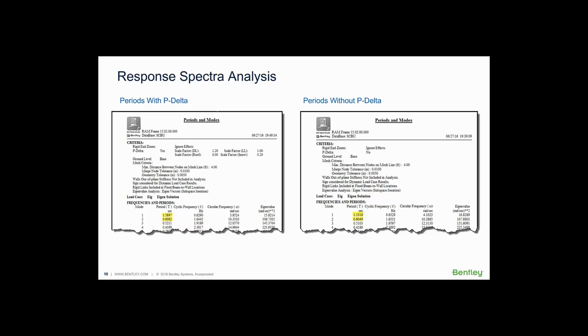That's what that B2 is attempting to measure. It's attempting to measure what my moments and my design forces would be if I include P delta versus not including P delta. That's what it represents. And so you need to calculate that for each given structure, and as I said, for each given story.